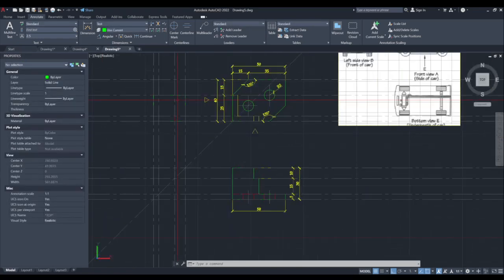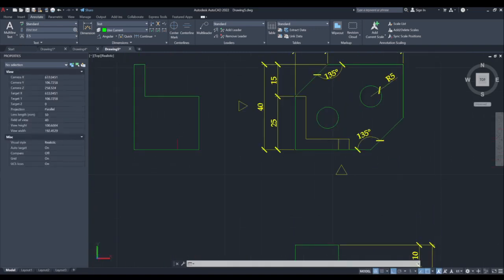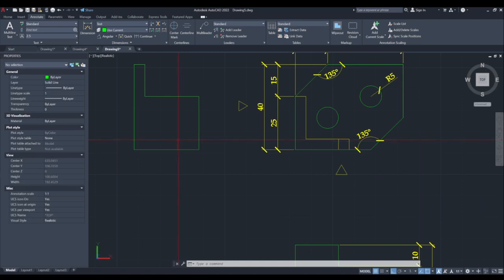Now I will now create another line. Okay, let's imagine that all the center line are off, so let's type this layer, and then center line is freeze. Okay, so now this is what we have seen here. Right, now create another line here, which is the invisible lines, or the hidden line.